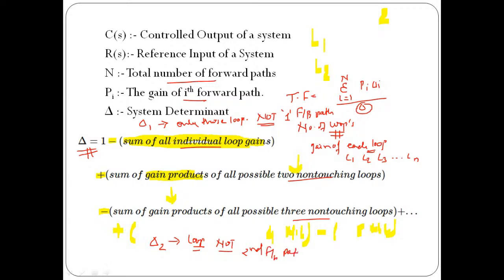So suppose in the structure of the signal flow graph, we identify that my second path is flowing from x1, x2, x3 and x4. Then no loop which encounters a node in common with that particular forward path is to be taken. Only the remaining loops we need to take care of while calculating the value of delta 1, delta 2 and so on.